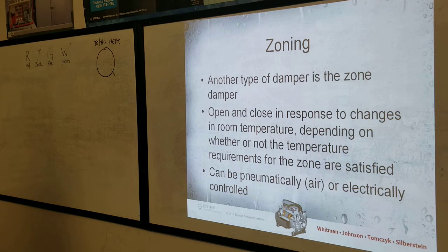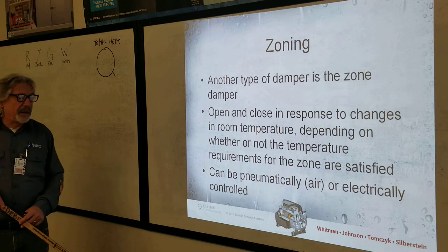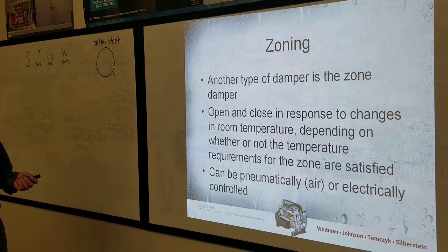It's a complete science, a branch of air conditioning. It's basically not that hard, and not that difficult to understand. Instead of using electricity to the thermostat, they use an air tube. The thermostat will sense the air pressure, and it will adjust the air pressure depending on whether it needs heating or cooling. Wow.